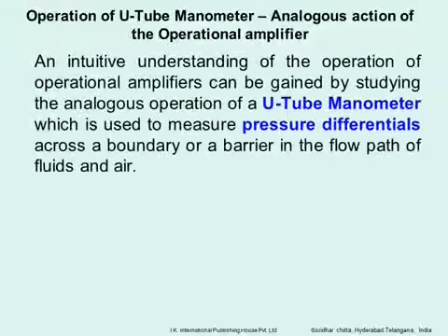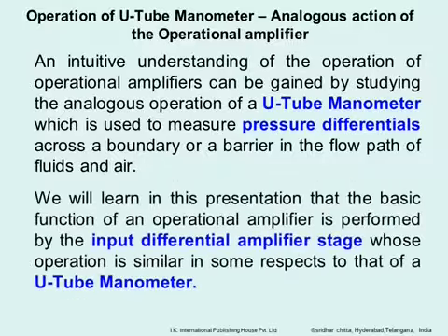An intuitive understanding of the operation of operational amplifiers can be gained by studying the analogous operation of a U-Tube manometer, which is used to measure pressure differentials across a boundary or a barrier in the flow path of fluids and air. We will learn in this presentation that the basic function of an operational amplifier is performed by the input differential amplifier stage, whose operation is similar in some respects to that of a U-Tube manometer.